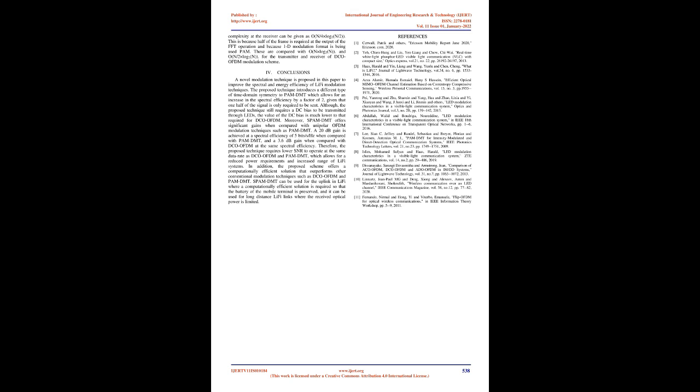In addition, the proposed scheme offers a computationally efficient solution that outperforms other conventional modulation techniques such as DCO-OFDM and PAM-DMT. PAM-DMT can be used for the uplink in LiFi where a computationally efficient solution is required so that the battery of the mobile terminal is preserved, and it can be used for long-distance LiFi links where the received optical power is limited.